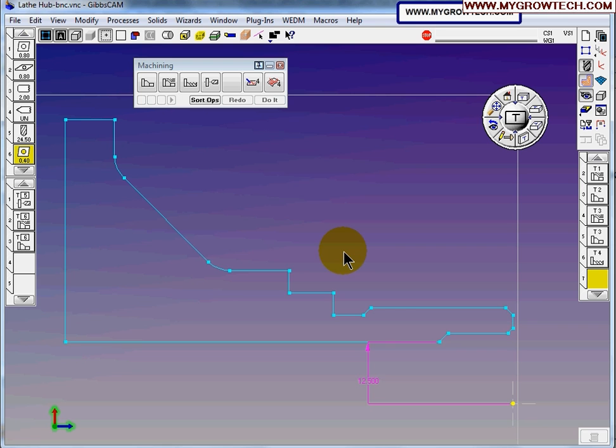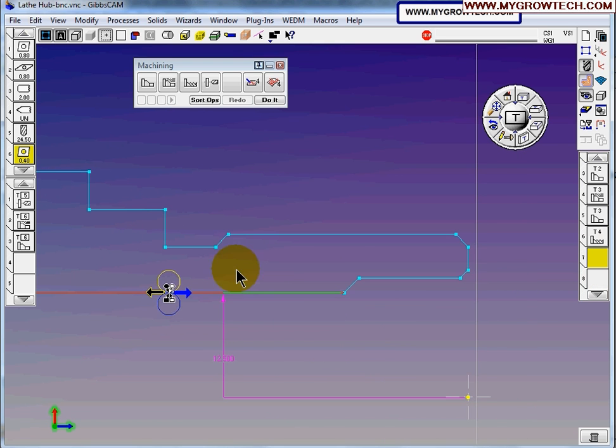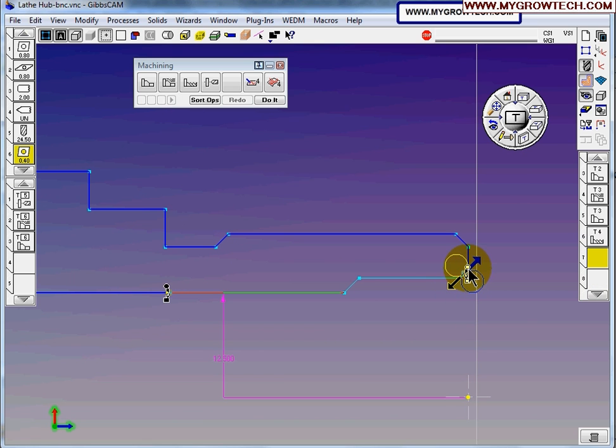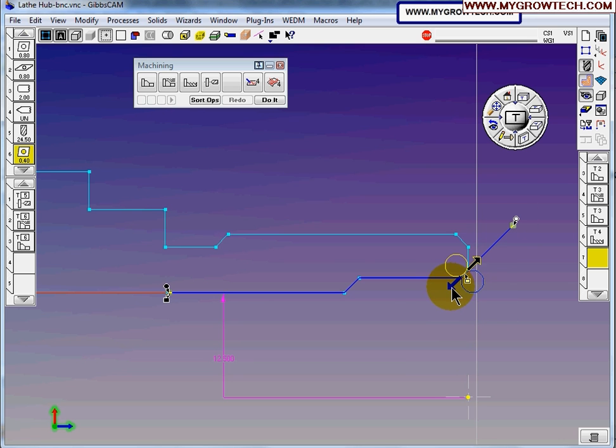Next, we will create the ID operations. Make sure the empty space of operation 7 is selected, because we're going to put the operations here. And select this line over here. I will adjust mine. Let's zoom out a bit. Starting features to here, the chamfer location, and extend it outside the stock. And make sure, of course, you are cutting towards Z minus, this arrow.